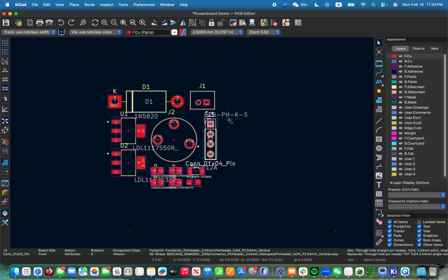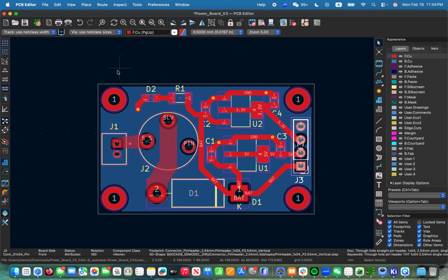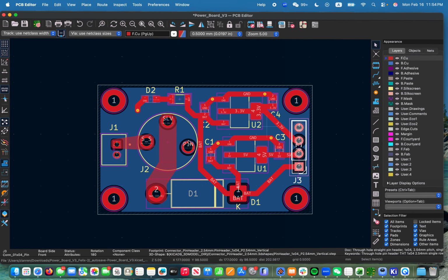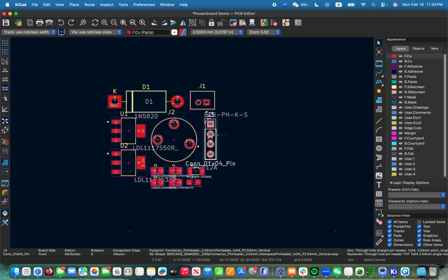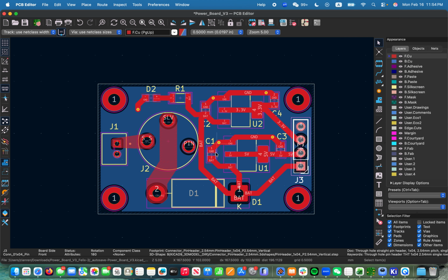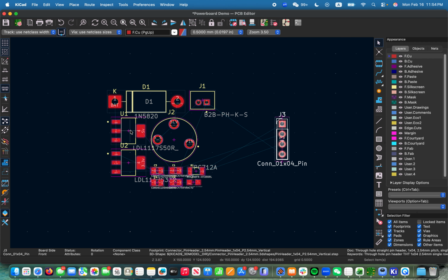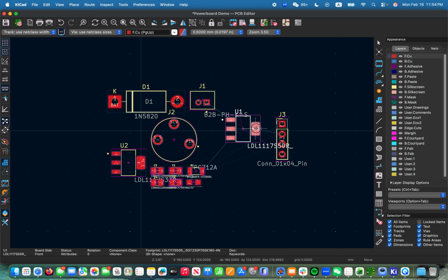So with our power board, we've elected to make something that's like a square. I'm going to make it a little bit more simple, but you guys can feel free to do whatever shape you want. So let's kind of mimic what the setup Felix has made for us here. So we are going to have this J2 connector in the middle next to the J1 connector, with a little bit of spacing for all the things here. Make sure that these LDOs can easily fit here.